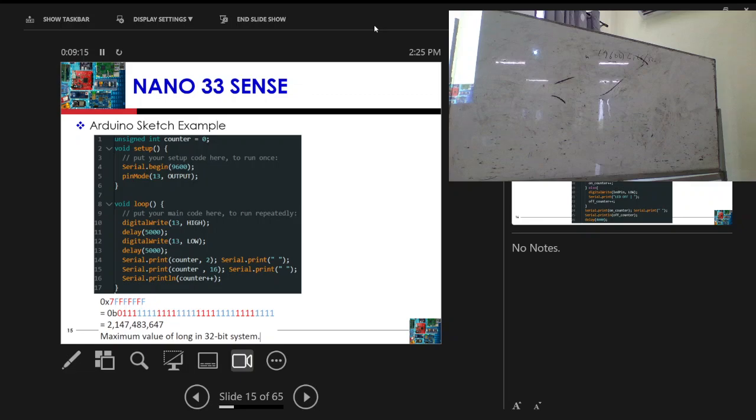So you are driving. I think I said that the digital pins serve as outputs, right? You drive the outputs. The analog pins serve as inputs. It gets something from the outside and then it feeds that to the MCU. So here for digitalWrite, we are writing to the digital pin, we set it as an output, and then we give the pin number, as easy as that. Here we are setting the digital pin high. We are driving it high, which means it's going to be on.